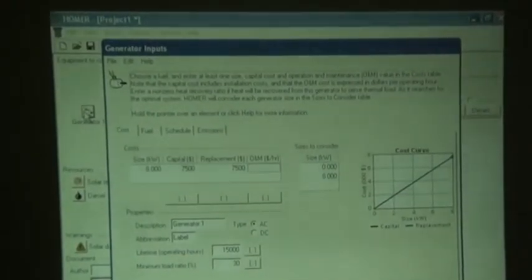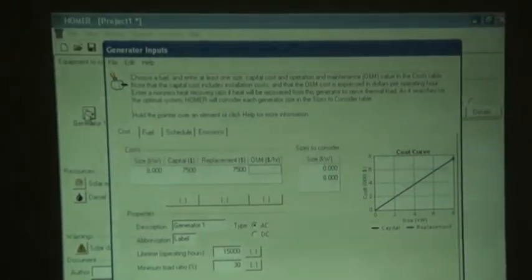Let's consider that the diesel genset is scheduled to operate for about 12,000 hours. For the 12,000 hours lifespan, take how much money you have to put into maintaining the diesel genset and divide that by 12,000, which gives you a per hour maintenance cost. To give an example, in Latin America, in some cases from good friends at Movista, the cost is as high as $3. We have seen the same cost structure in some places in Central Africa, Sudan, Central African Republic and so forth, as high as $2.5 per hour.